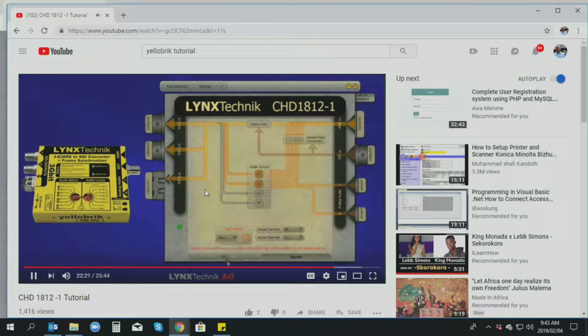do that. So you can just ignore those, and if there's no audio present, this wouldn't be lit up anyway. This is obviously showing audio present, so it's lit up, and you can see where you're embedding those. This again is sample rate converters. They're on and off typically. With encoded audio, as I mentioned before, with AC3 and Dolby Digital and any encoded audio format, you do not want to sample rate convert those audio streams, because they will be destroyed. Typically PCM audio does go through a sample rate converter for the purposes of locking the audio.